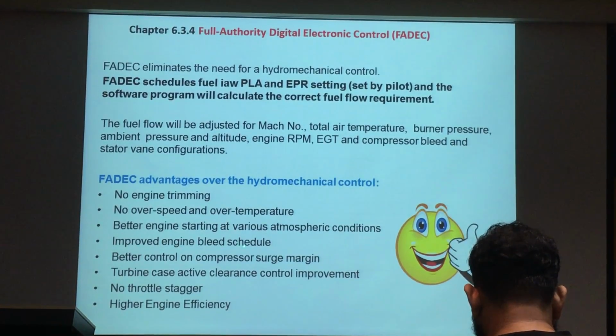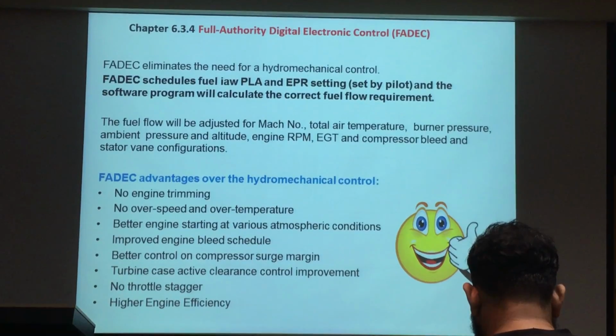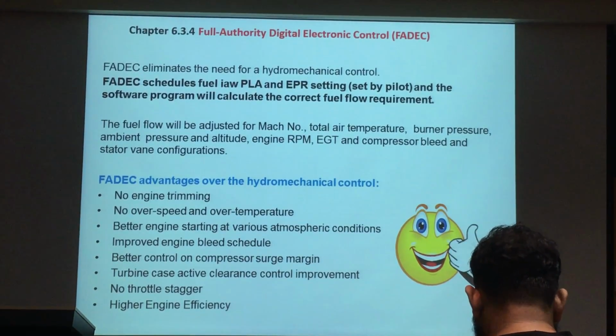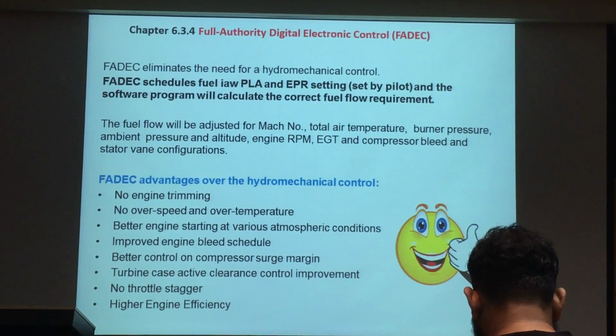Improve the engine bleed schedule. Remember engine bleed, VSV actuator control, or the variable pump control. All automatic now. Last time it was mechanical, you had to do rigging, push-pull cables, all these things. Now no need, the computer takes care.